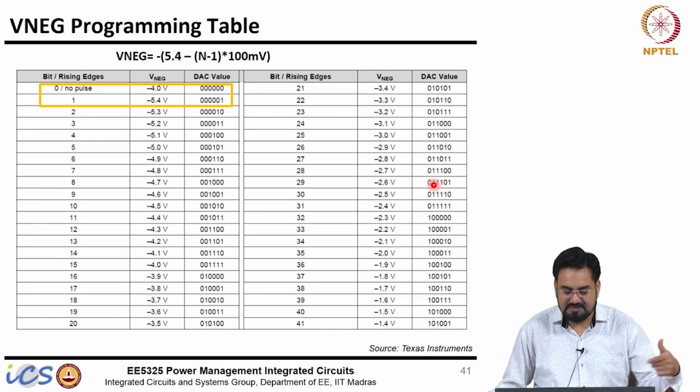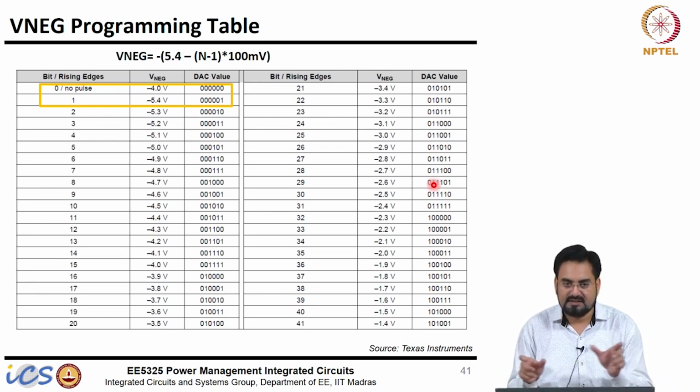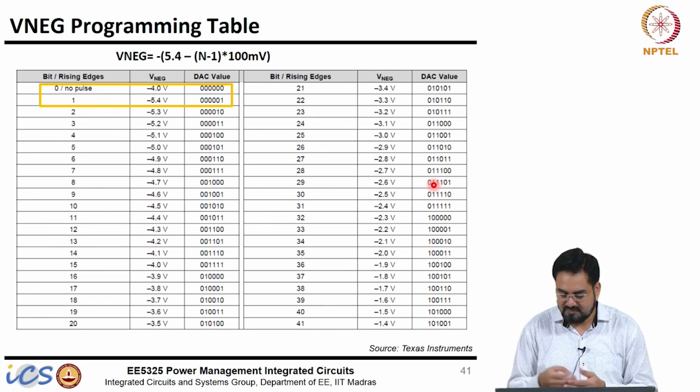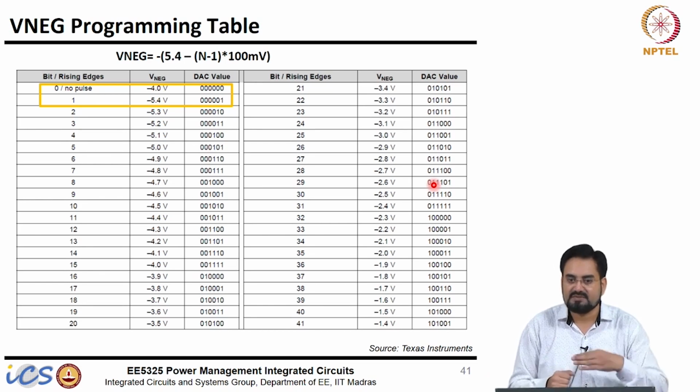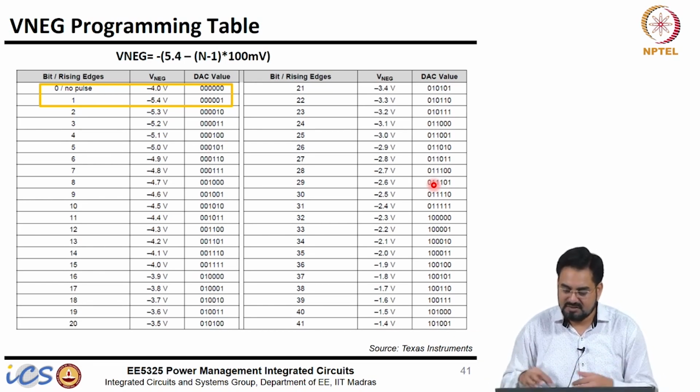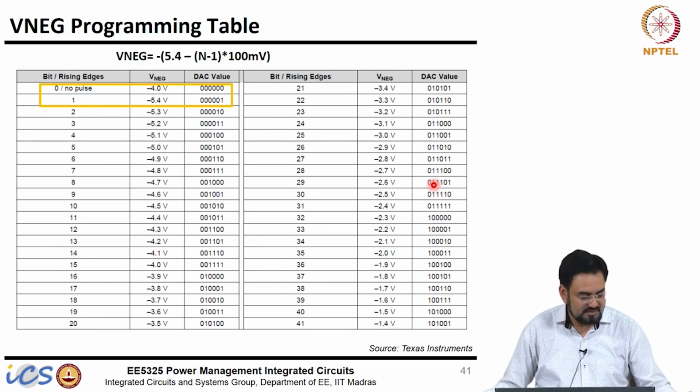These pulses will basically be counted and then latched, and we know that these voltages can be programmed using a DAC. Let us say a feedback resistor: you can just program the feedback resistor and get different values. Those will control these voltages, using a voltage DAC or resistive DAC, or you can change the reference also if you have one.